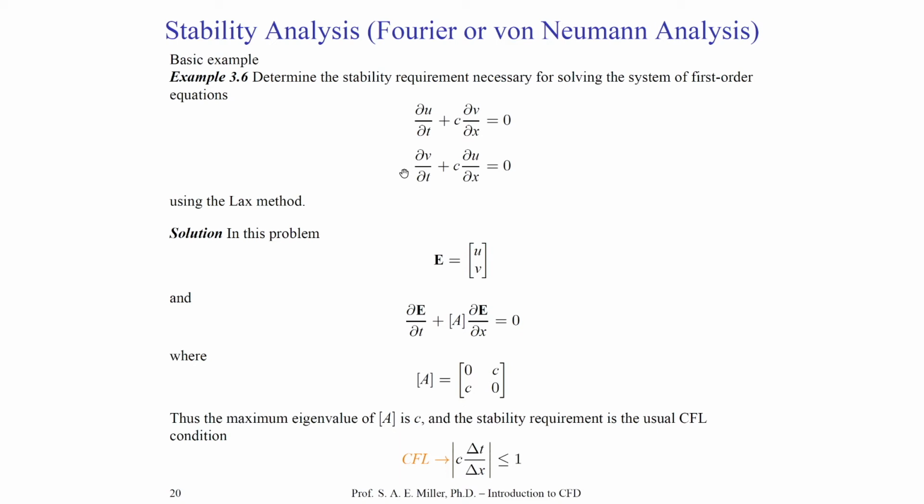You'll see that there are different stability requirements for different types of numerical schemes. For example, the classic Runge-Kutta scheme has a maximum CFL number for stability of approximately 1.5. There are many other types of schemes. And of course, this type of stability analysis can also be applied to implicit schemes. It can be shown using the same type of analysis for linear equations that they are unconditionally stable. They're always stable.